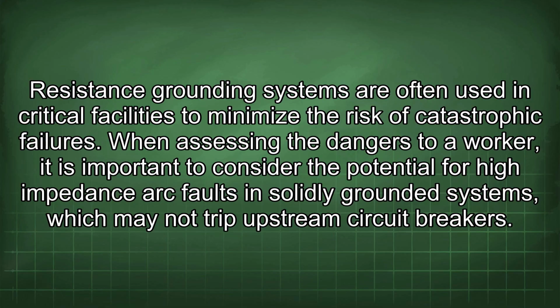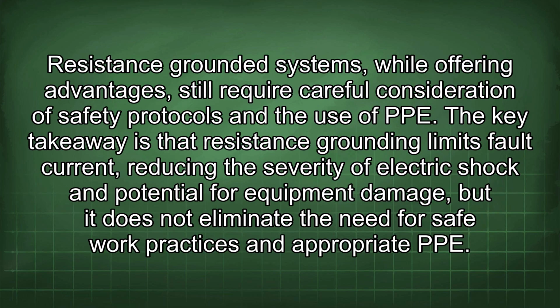When assessing the dangers to a worker, it is important to consider the potential for high impedance arc faults in solidly grounded systems, which may not trip upstream circuit breakers. Resistance grounded systems, while offering advantages, still require careful consideration of safety protocols and the use of PPE. The key takeaway is that resistance grounding limits fault current, reducing the severity of electric shock and potential for equipment damage, but it does not eliminate the need for safe work practices and appropriate PPE.